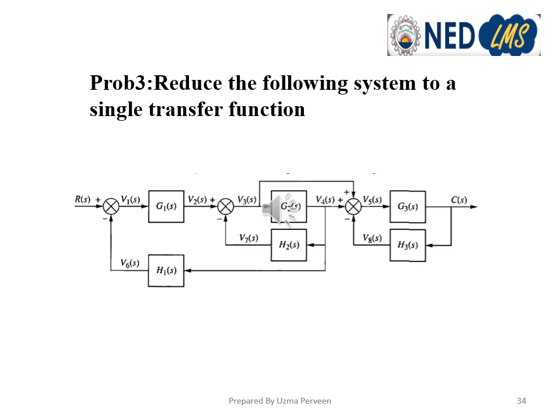If we have a feedback loop without any block, directly connected output to input, then it means that H(s) equals 1. Similarly here, if we move point V3 beyond the block G2, then in the next right parallel path, we combine this parallel path using transformation 2, combining blocks in parallel.